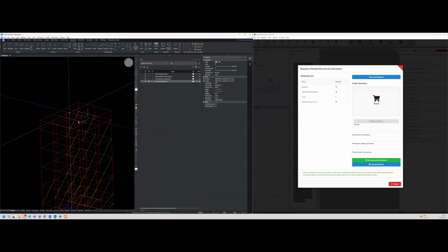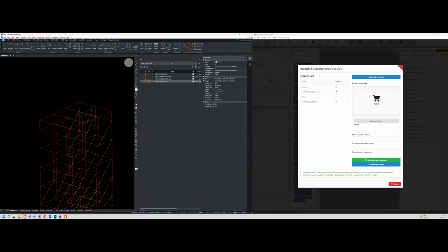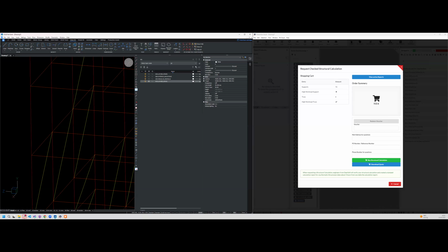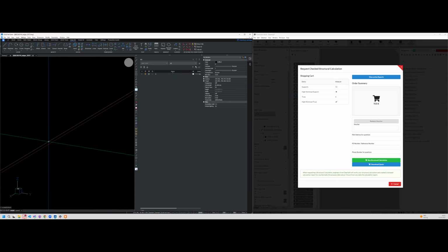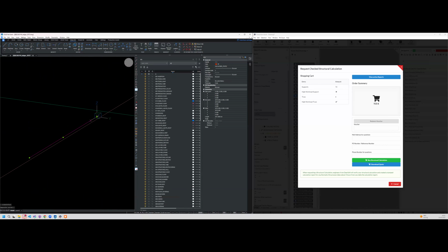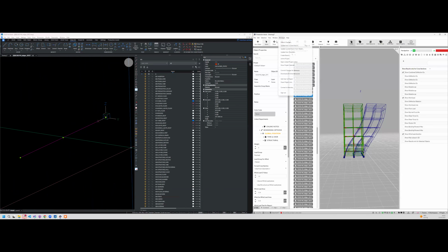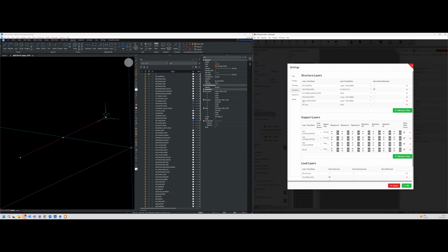So what I need to do in my own world, in my own symbols, is basically add these center lines in here. On a really basic level, double clicking and then drawing these lines so that I can use them for the calculation. There is a specific way to map the cross section. I already showed you the settings, and in there, for a specific given layer, you can define the cross section that should be used.